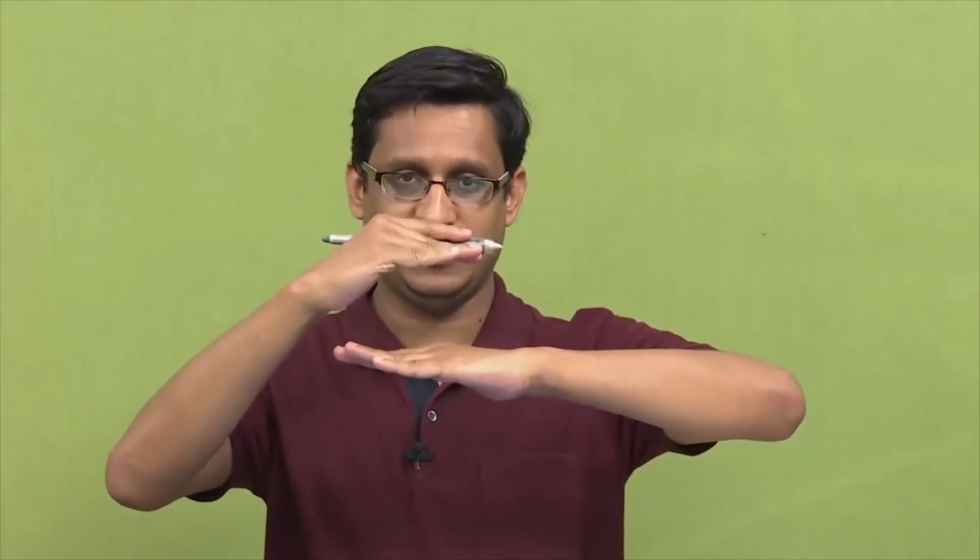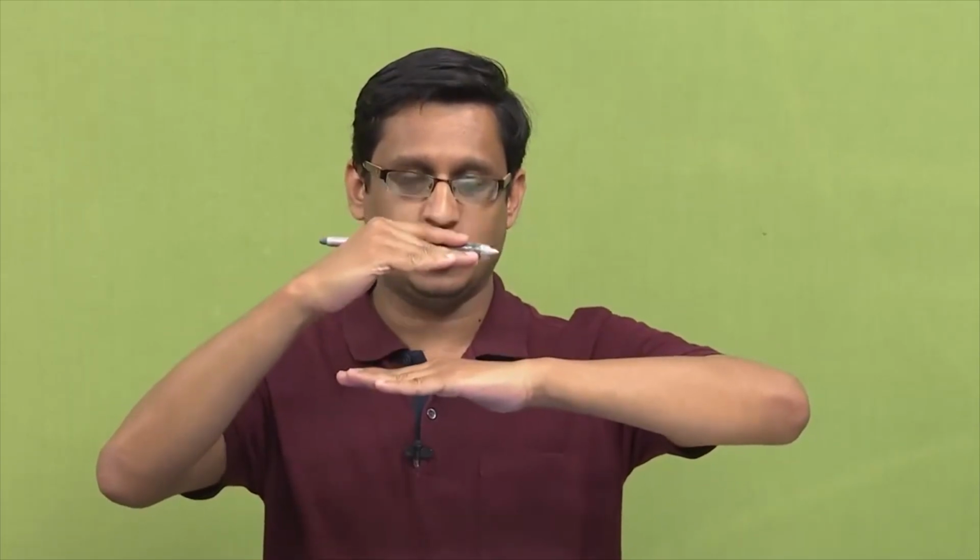So, all that we did was to send in an electromagnetic wave at an angle theta I, and what we managed to obtain is a functional dependence on x, which is a standing wave, and this standing wave will go to 0 at many places. But if I now were to place a perfect electric conductor at one of the places where the electric field is going to 0, then what I have done is to essentially bound my electromagnetic wave between the two walls, and this particular pattern, which is a function of x, would move along the direction z, indicating a travelling wave along z.